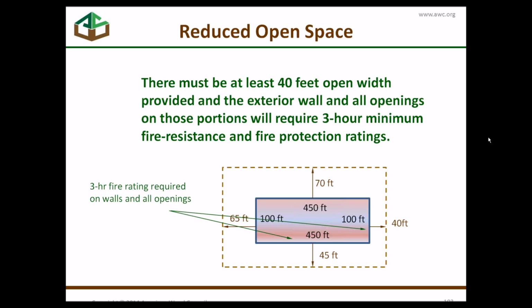That's a great question. Actually, if you have a width of 60 feet, as we've seen, you get lots more benefits. That's where you kick into the unlimited area building provisions. The question might be, if you're between 30 and 60 feet, then maybe you should get some additional credit for that. And I think the code does actually give you some credit for that. I'm going to flip through right now and look real quick.